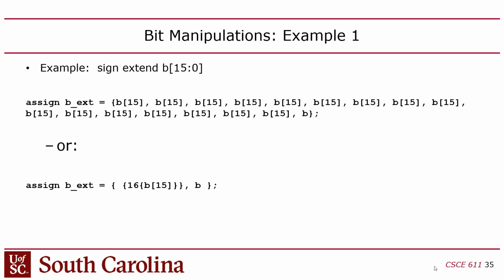So obviously you just change the bit you're duplicating and the number of times you're duplicating it. But this is using the duplication operator to duplicate the sign bit to convert a smaller number of bits to a larger number of bits without changing the sign. Okay?